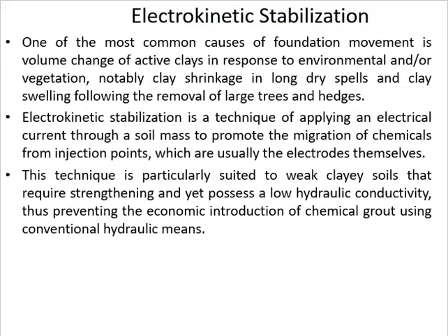Next method is electrokinetic stabilization. One of the most common causes of foundation movement is the volume change of active clays. Electrokinetic stabilization is a technique of applying an electrical current through a soil mass to promote the migration of chemicals from injection points using electrodes.